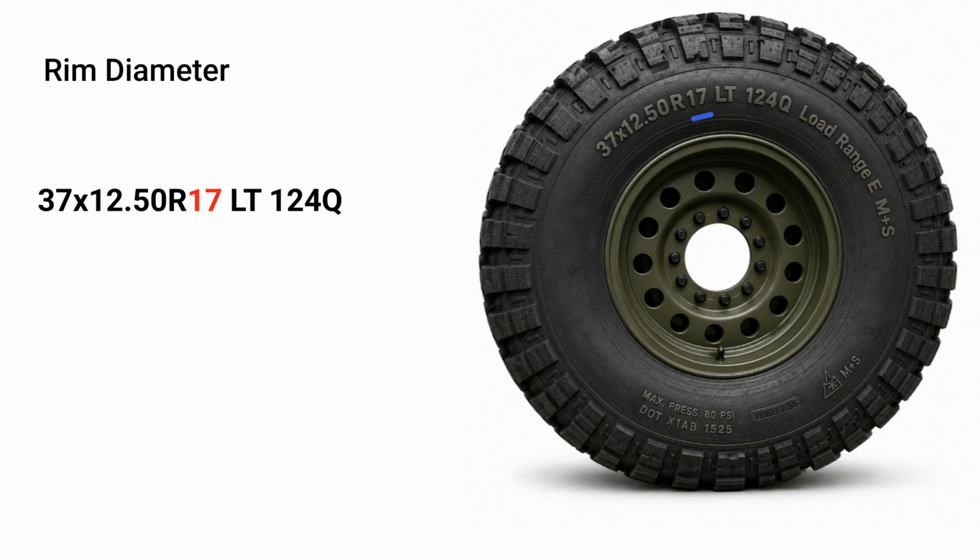Next in the marking, we see the number 17. This represents the rim diameter, measured in inches. It means that the tyre is designed to fit a wheel rim with a diameter of exactly 17 inches. It is important to remember that rim diameter is not the overall tyre diameter. The overall tyre diameter in this example is approximately 37 inches, while 17 inches refers only to the wheel on which the tyre is mounted. Correct rim diameter ensures proper bead seating, safe fitment, and compatibility between the tyre and wheel.